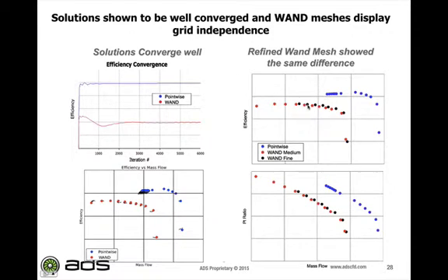That new speed line is here in black. First thing to note is that when it comes to the efficiency, the choke is actually not too much different than our original mesh. Please note that we did not run this fully to stall, so we did not really check the range for the fine mesh. But from a higher level, we can see that increasing the amount of elements in the flow field did not really change the results significantly. So there must be something else here.